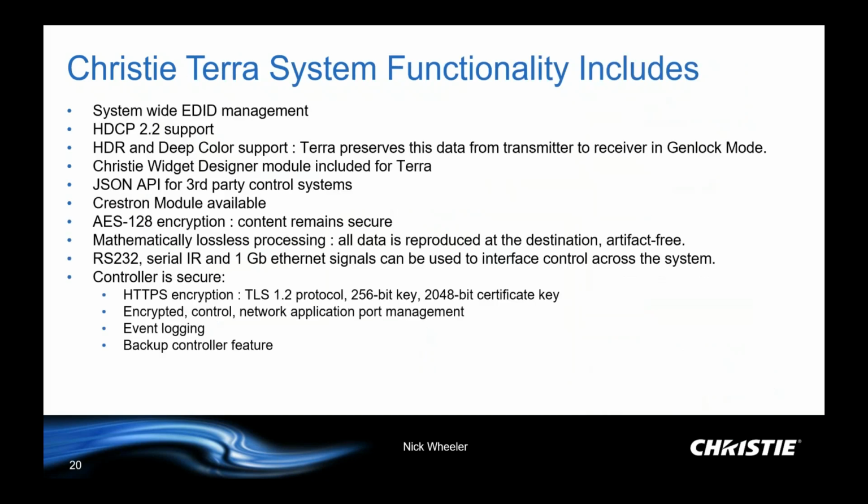So some of the functionalities I've already talked about. System-wide EDID management, where you can actually pick the EDID from a specific transmitter and send that to one or more. You can also pick the EDID from a receiver, and send that to one or more transmitters on the network.